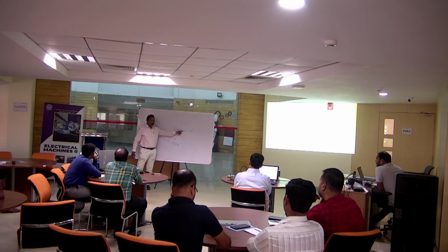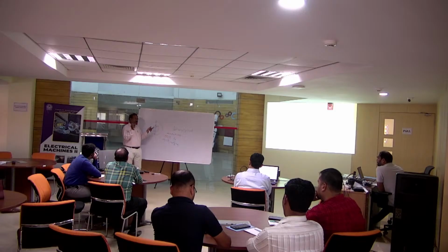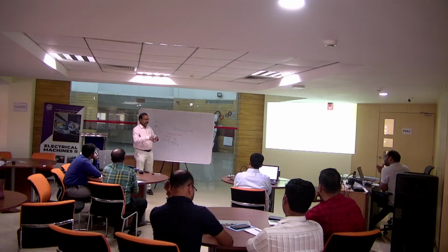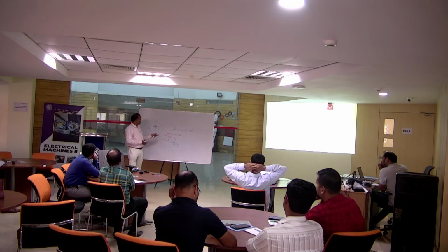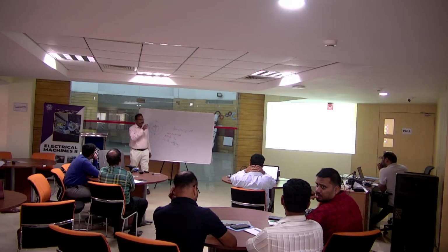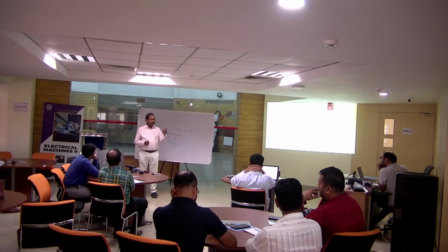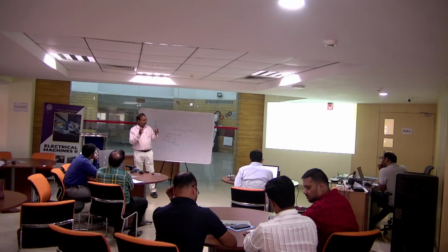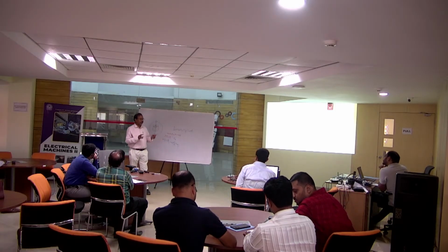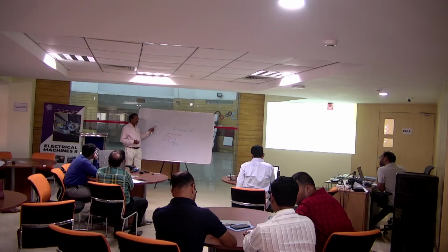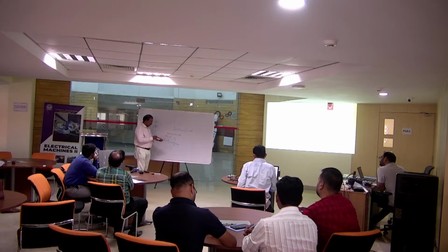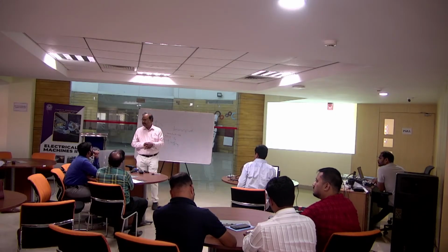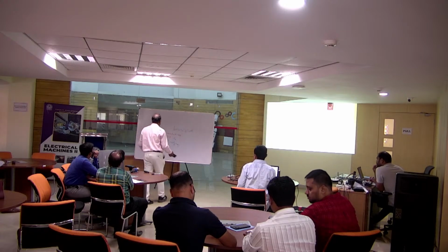This is a pulsating magnetic field. This pulsating magnetic field is equivalent to two rotating magnetic fields, both of the same magnitude, rotating in opposite directions, 180 degrees apart. This is what you get in a single phase induction motor, like a fan motor. One single coil will not give a rotating magnetic field, so we have two coils, separated by a capacitor, so two currents you get, phase split. Now when two magnetic fields are rotating in opposite directions, what happens? Two torques, double field.